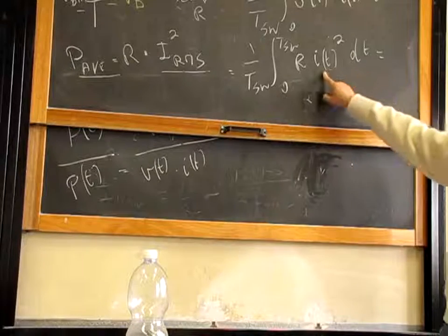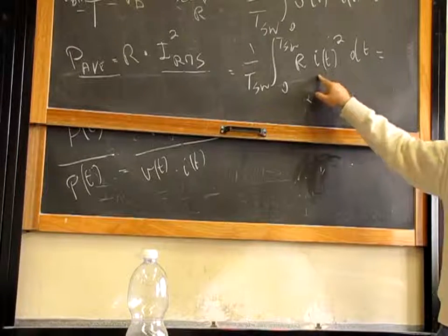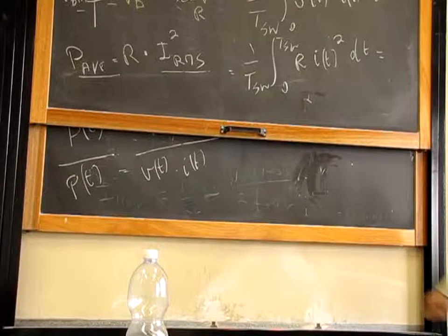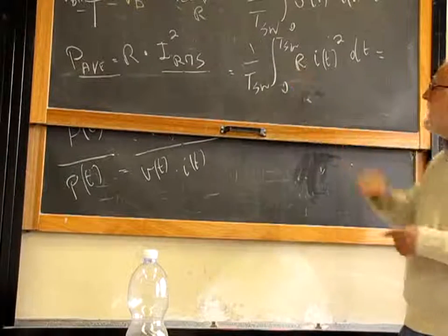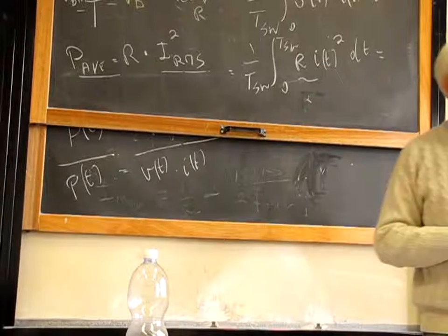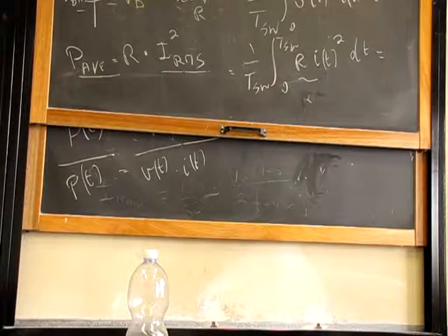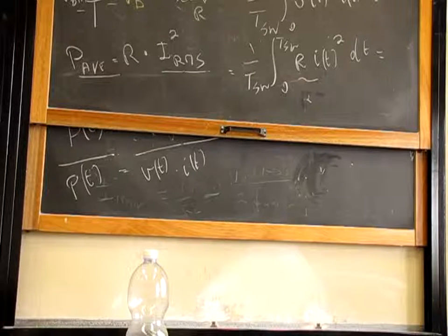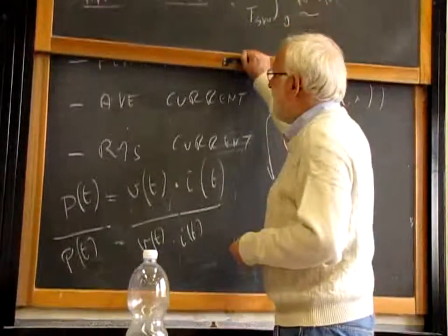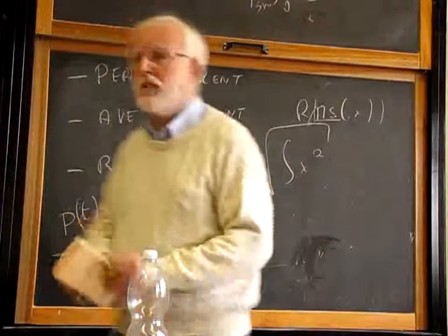Anyway, this is the reason why we need RMS current. RMS is applied every time we have something like a resistor. It means in any winding, inductors, transformers, the wire looks like a resistance, has a resistance, and in MOS transistors. An MOS transistor, when the channel is completely formed, in full conduction, looks like a resistance. Very small value, but it's a resistance. So we need both RMS and average current. Peak is easy. Peak we already have.